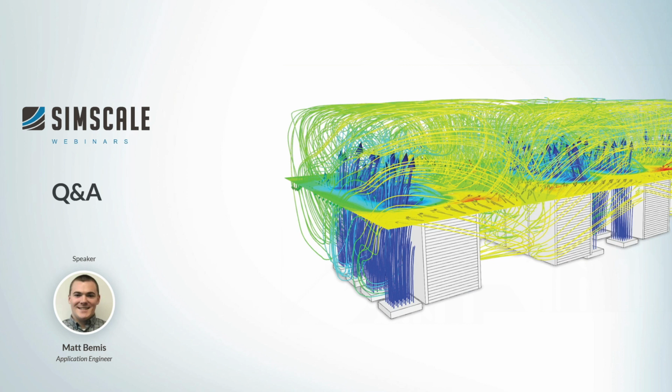We thought, well, maybe if we just put a ceiling plenum in, can we actually improve the performance with the same amount of air, the same amount of cooling capacity? Ultimately, it worked. The answer is yes. We put in a drop ceiling, and essentially we're able to get rid of that recirculation you see on racks, which is excellent. So let's jump into Q&A and go ahead.